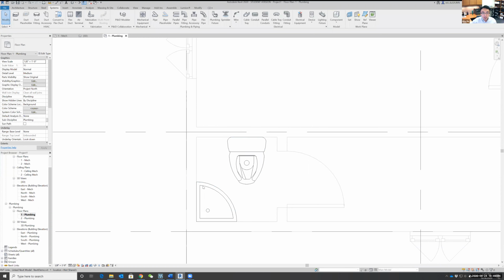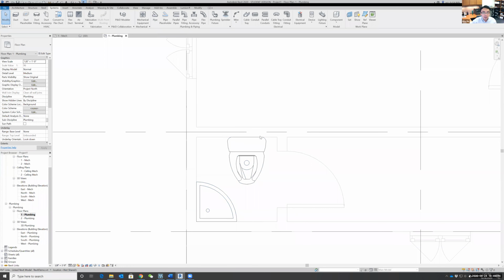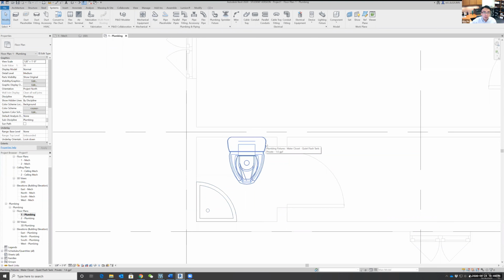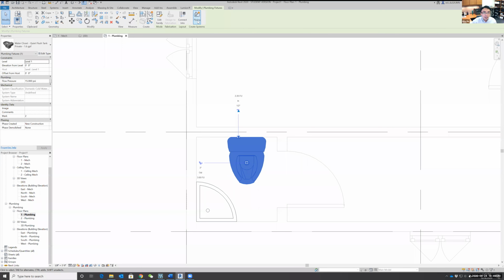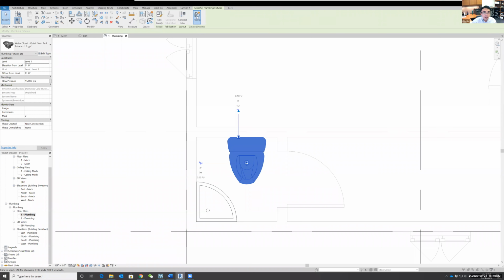And similarly, we need the water pipes to connect everything, right? Let's say you also have the shower and everything. We can use the water pipe. Once again, you can definitely use the manual way to do it, but you probably know already, we can also automatically generate the layout for that. So let's just close this one and just go create a system called a piping system.